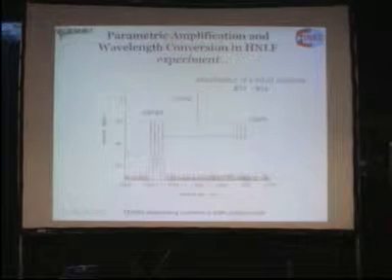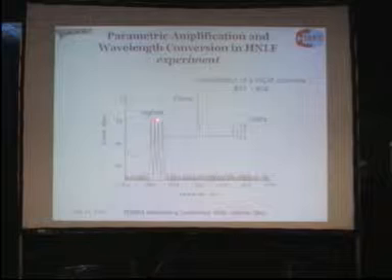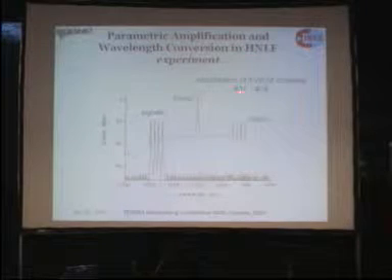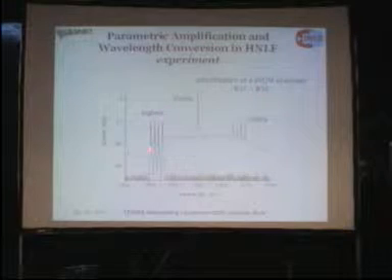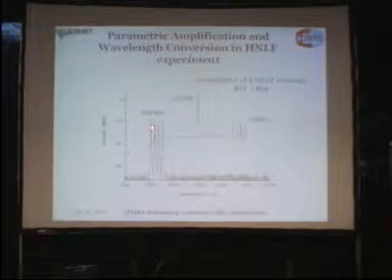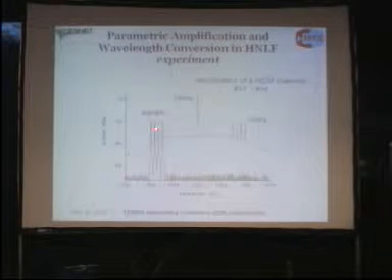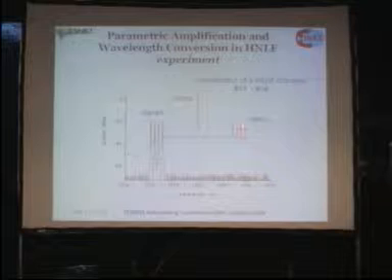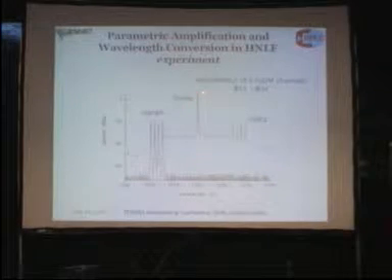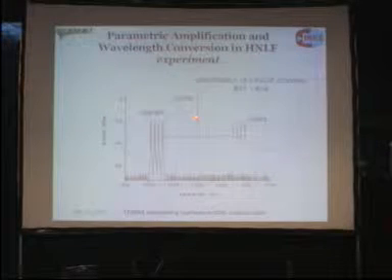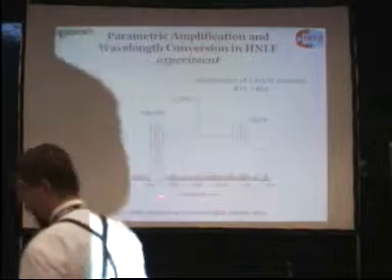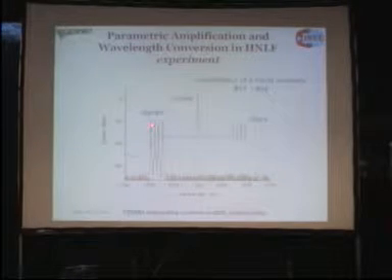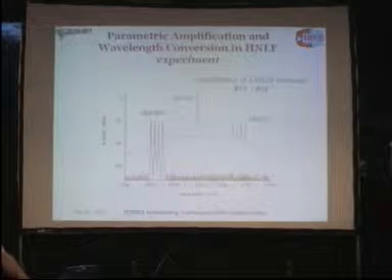This is just an experimental demonstration where we amplified two WDM channels starting at channel number 31 according to the ITU grid and ending at channel number 34. The black lines are the optical spectrum analyzer traces recorded at the input of the highly nonlinear fiber, and the red traces are when one pump was on. The pump was at 1560.1 nanometers, so the fiber was the one with zero dispersion wavelength at 1560 nanometers. You can see that the amplification was approximately 10 dB in that case.